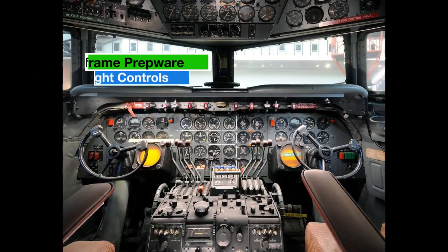Which statement concerning the 100-hour inspection of an airplane equipped with the push-pull tube-type control system is true? The threaded rod ends should be checked for the amount of thread engagement by means of the inspection hole provided. When the lift of an airfoil increases, the drag will also increase.